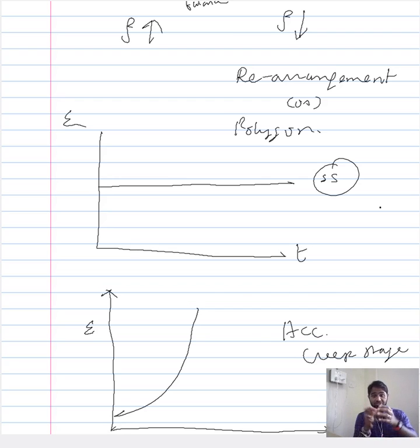In stage 1, you have the instantaneous creep stage. Your behavior is relatable to the mechanical behavior involving the stress-strain curve. The same carries over to stage 2, the transient creep stage, wherein because of the stress that you impose, the dislocation density proportionately increases. Because of the increase in dislocation density and the complexity in their interaction, their movement gets impeded, thereby restricting the plastic deformation. So all these happen at stage 1 and stage 2 of the creep.